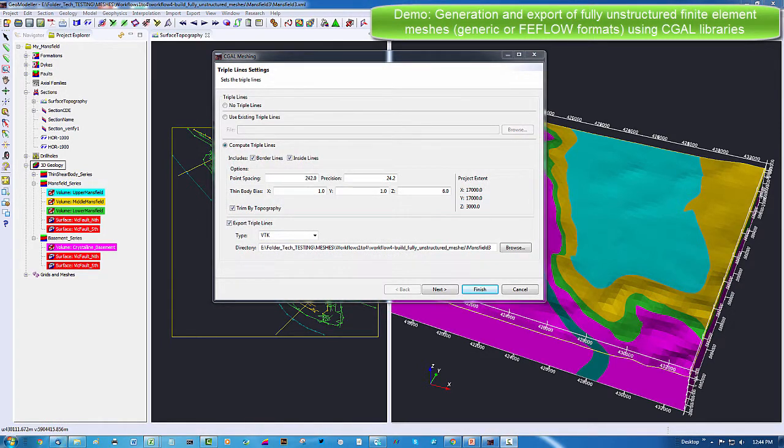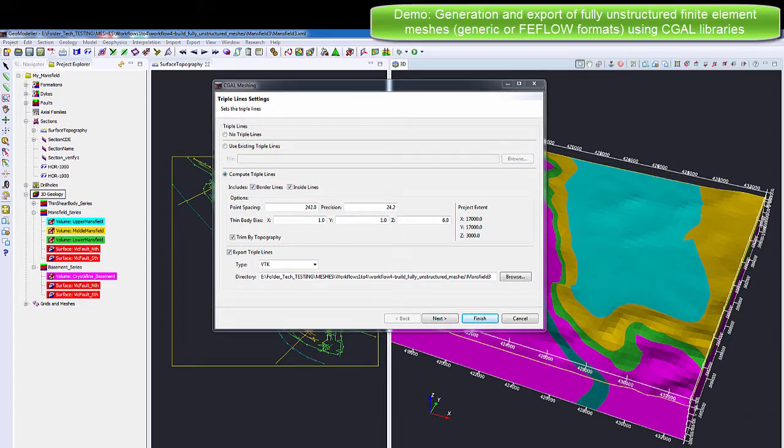The first question is whether or not we're going to select to preserve triple lines. Triple lines are where 3 geological compartments, or 2 compartments and air, come together, and it's about asking to preserve the exact location of the implicit surface as solved, and therefore delivering these will include a very aesthetically neat mesh. However, it's not compulsory to compute including the triple lines.